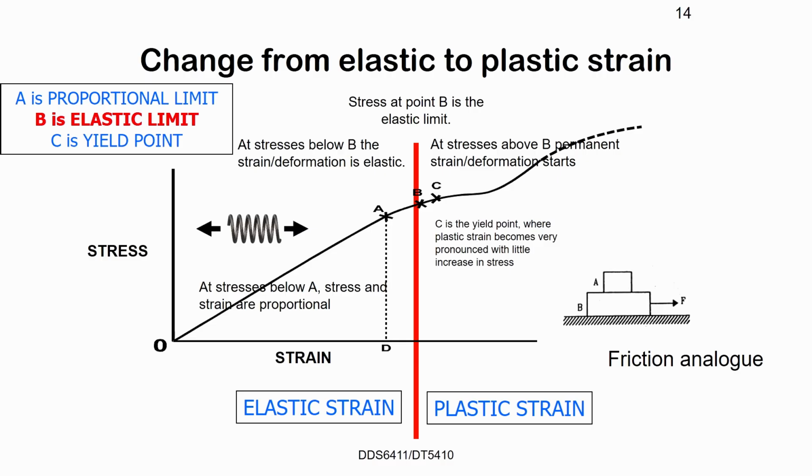We always try to design using the yield stress. We want to make sure all the stresses in every component do not reach their yield stress. Then your structure would be safe, because we know that once you remove the load, we're going to recover all the deformation.